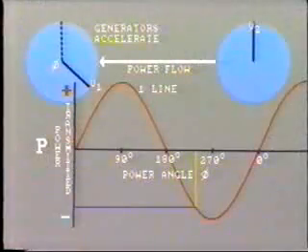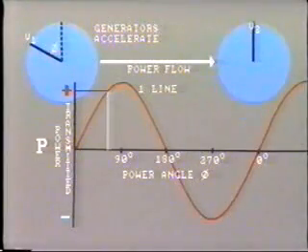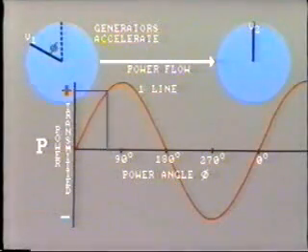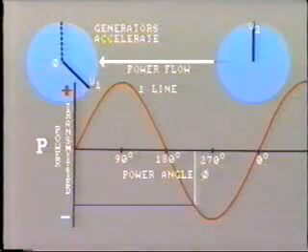This is instability. The reversal of power flow in this line will probably create large disturbances on other parts of the system. Hopefully, the generators at bus 1 will pull into phase and remain in phase as they recover their original position. However, experience tells us that this is not likely to happen, and the generator will probably continue to accelerate and remain out of step with the system. This condition is known as slipping a pole and is the symptom of instability. The only remedy is to disconnect the unit from the system and then resynchronize.